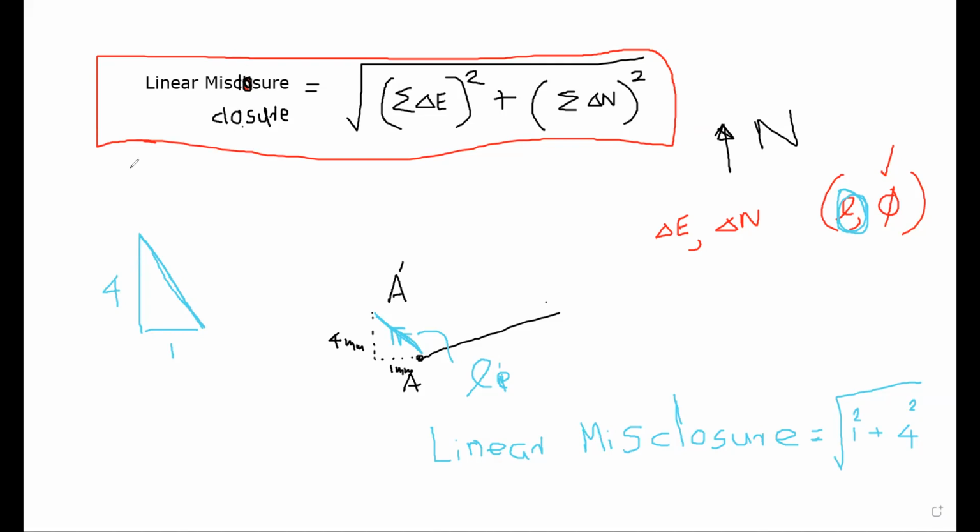So we can calculate delta E and delta N, the summation. The summations give us a meaning, that is the total error in the east-west direction and the displacement in the north-south direction. We don't expect any final displacement as we stop at the same point we started.